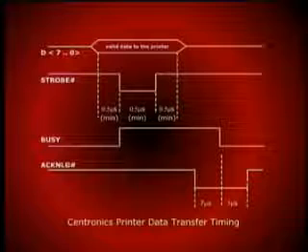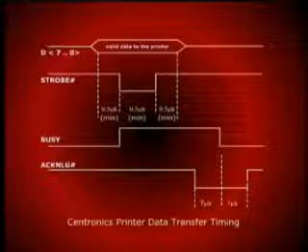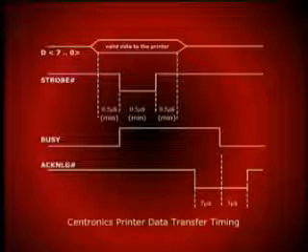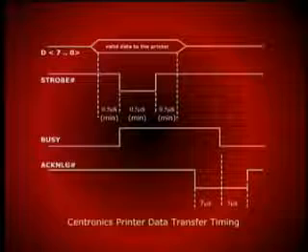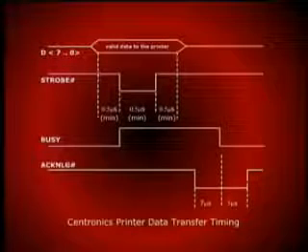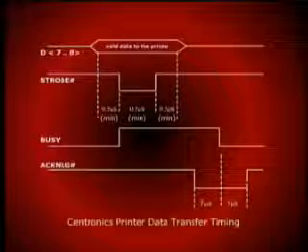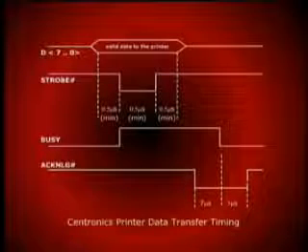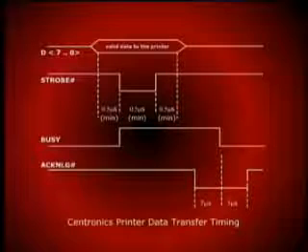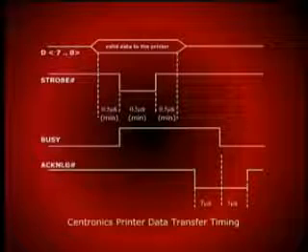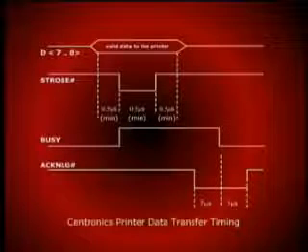When this character is completely received, the acknowledge signal, which is physically available on pin 10, goes low, indicating that the transfer is complete. Soon after this, the busy signal returns to logic 0, indicating to the CPU that a new transfer can be initiated. The busy signal is more suitable for level trigger systems, while the acknowledge signal is better for edge trigger systems.